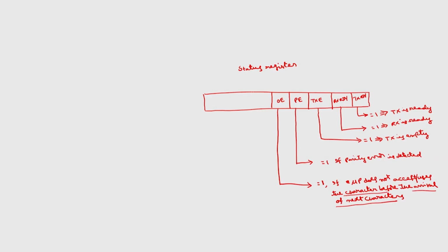Then we have framing error. This is equal to 1 if the stop bit is not identified. Then we have sync detect.